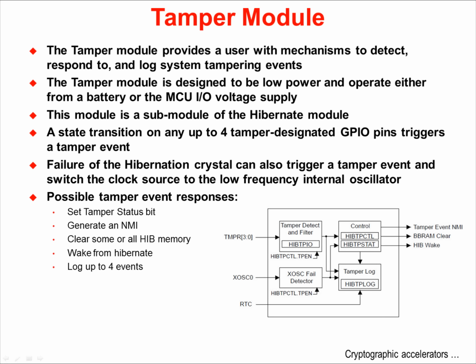There are several possible responses to tamper events. The module can set the tamper status bits, it can generate a non-maskable interrupt, it can clear some or all of the battery-backed memory, it can wake from Hibernate, it can log up to 4 events.